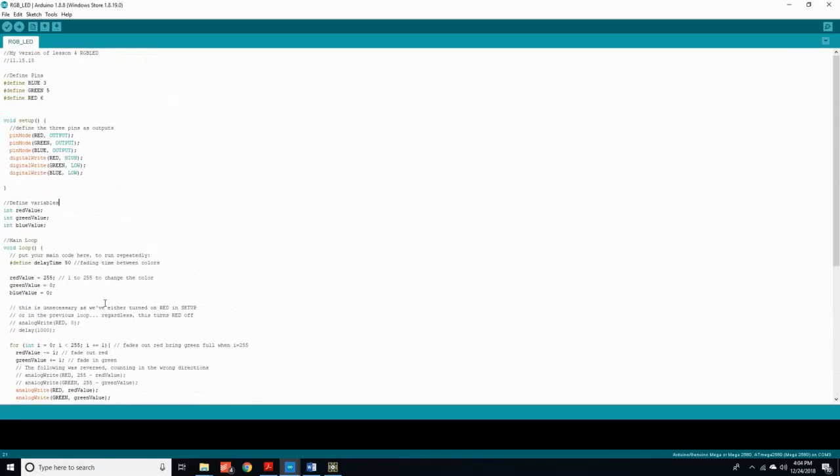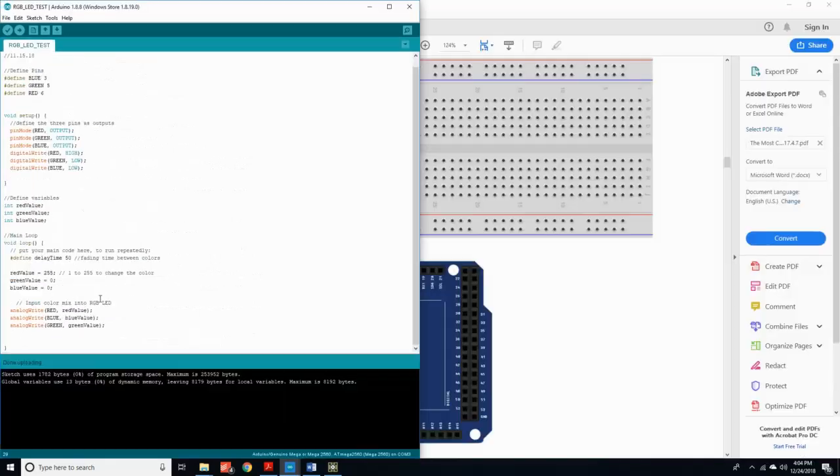All this script is going to do is set the red value to 255. Once you upload it, the LED on the Arduino should be red. And you can mess with it. You can put 255 on the green value or the blue value, whichever one, to make sure that it's working, or if you just want to play around.